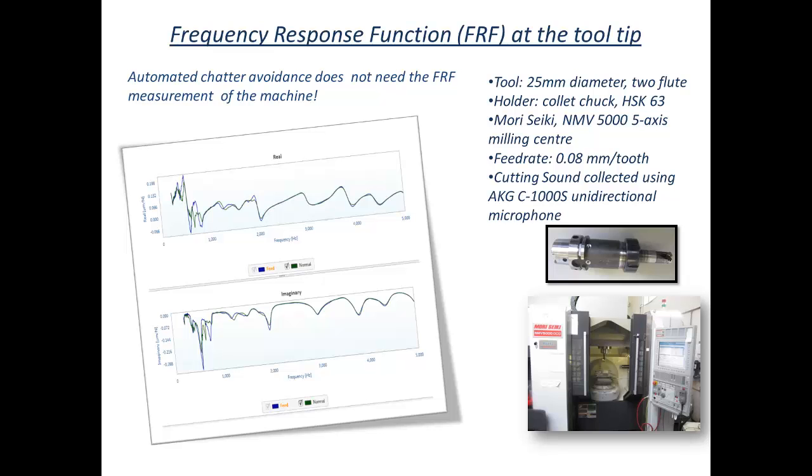A cutting tool with 25 mm diameter having 2 inserts is mounted on a 5-axis machining center. The cutting sound was collected using a unidirectional microphone, and the feed was 80 micron per tooth during the cutting of steel.